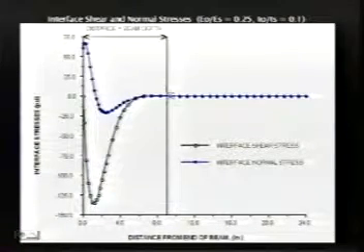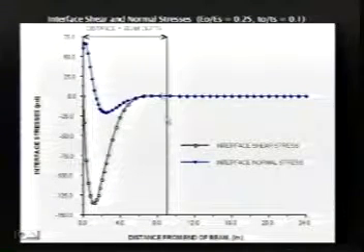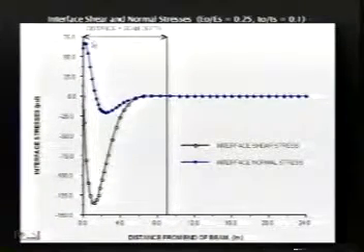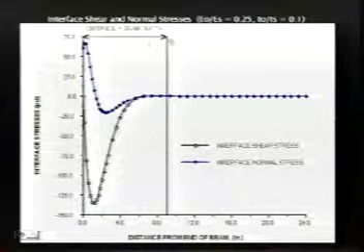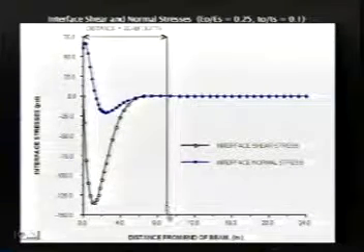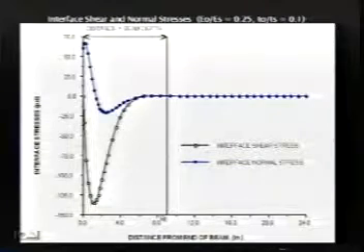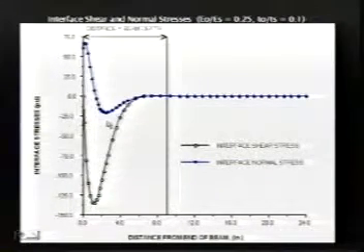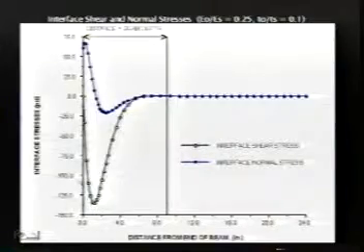This really summarizes one of the main points we want to make. If this represents the depth of the slab or the beam, maybe it's about 8 inches in this case. I think we show about 8.5 inches, an 8-inch slab and maybe a 1/2-inch overlay. You'll notice that these are interface shear stresses in white. The blue represent the normal stresses. The important thing to note is that these stresses are the highest magnitude right near the edge of the slab.